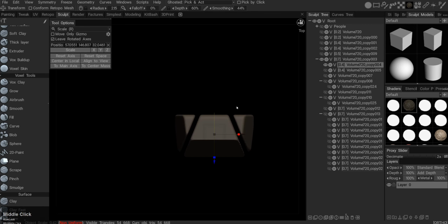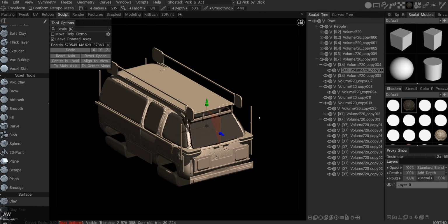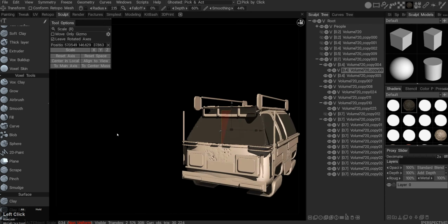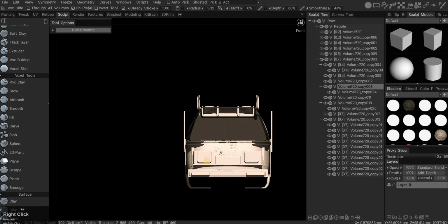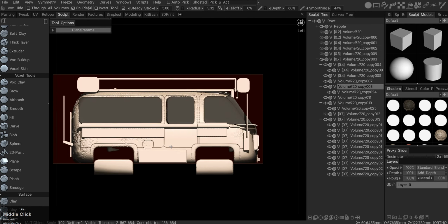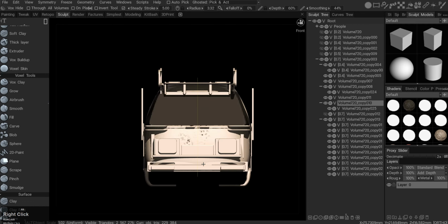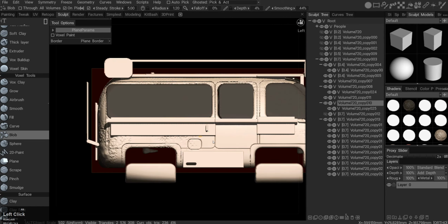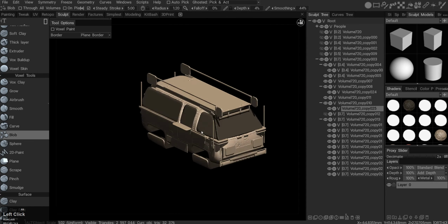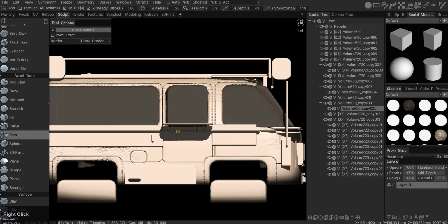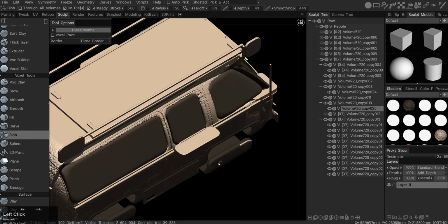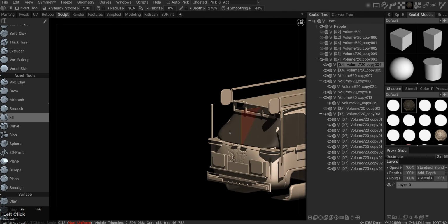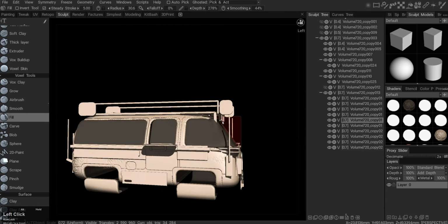Playing with some materials, separated that bit. I didn't like that separation. So now I made the front window much bigger to make a seamless windshield around the front, and just add in some details. Now you'll see I always have rounded edges on, and you can activate them by pressing the E menu, and there's a rounded edges menu. Okay, so now just combine those two windows, and I'm smoothing in between.